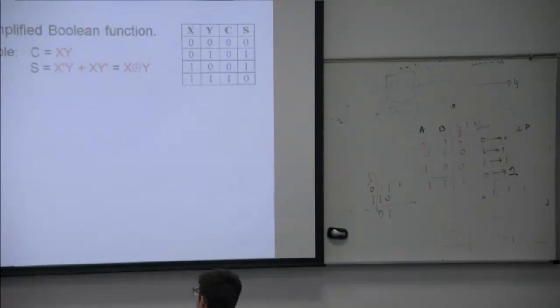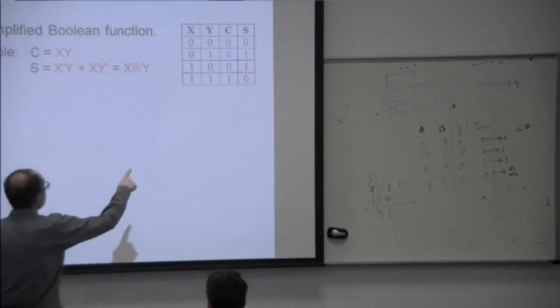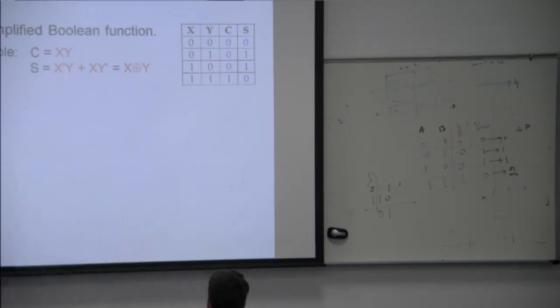Can you see? Okay, now gate level, half adder. This is the gate level. Now if we have this function, S stands for what? Sum. C stands for what? Carry. Now we have a single one. So what is C? C is X Y. And then what is S? S is X bar Y plus X Y bar, the XOR. Got it? Any question? Simple.